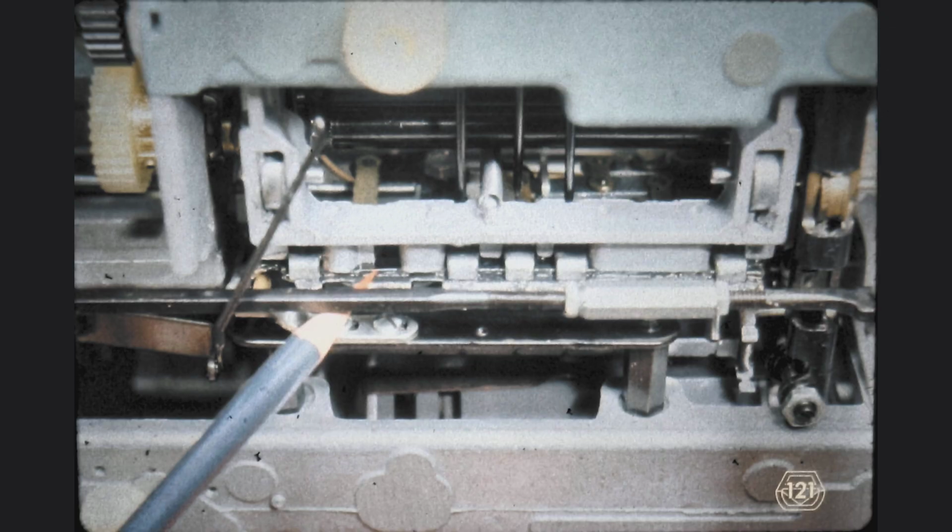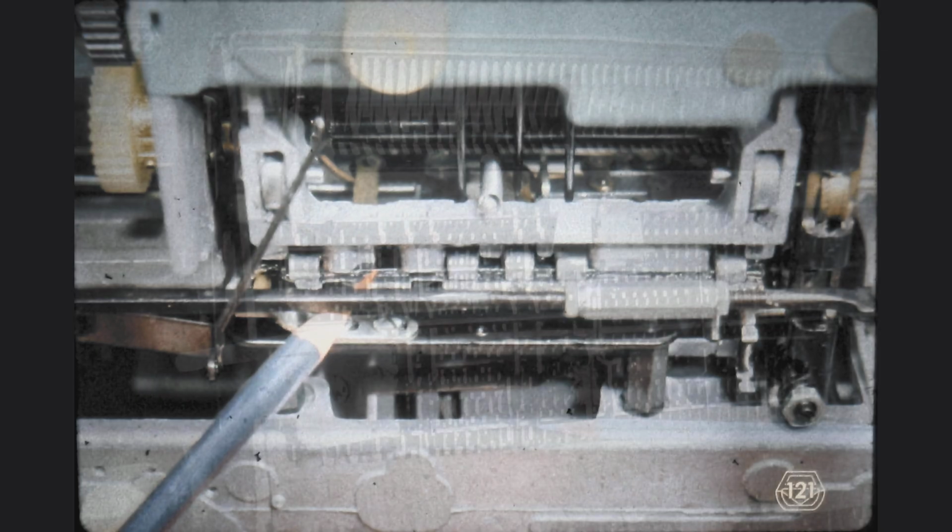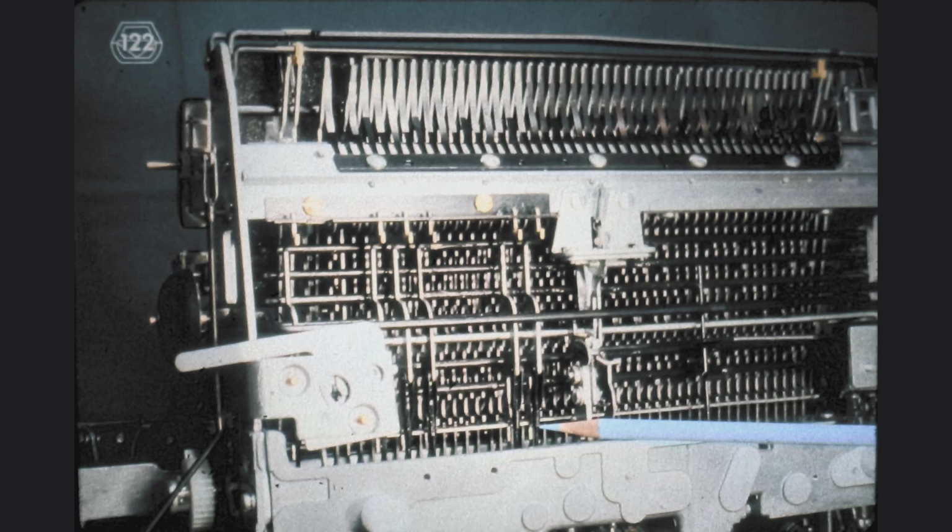When we have a plate to the rear of the latch bail, we must be careful not to have any loss of motion between the latch interposer link and the selector latch. The length of the latch links can be adjusted by these clevises. These links control the front-to-rear rest position of the selector latches on older machines. On newer machines, which come equipped with a back plate on the latch bail or cam follower, they control the amount of lost horizontal motion which may exist during the latch selection process.